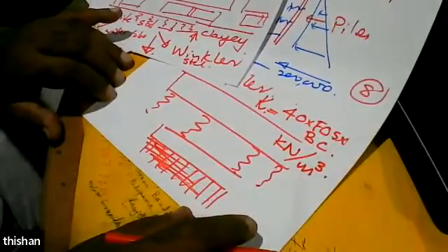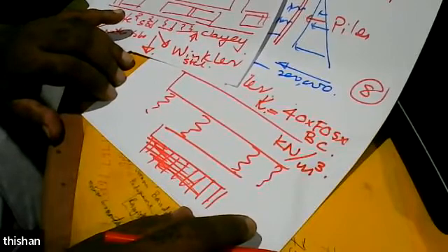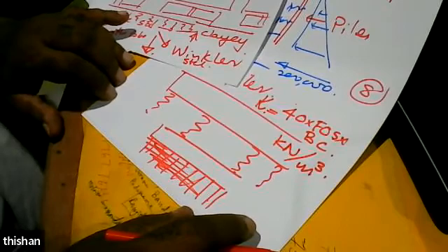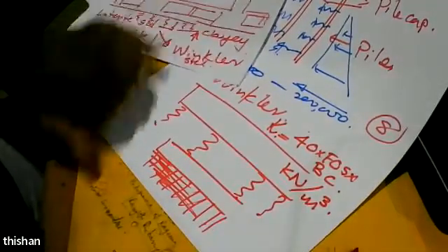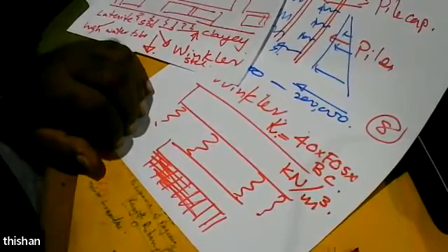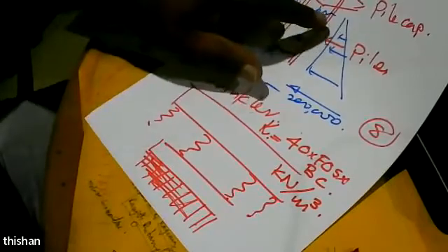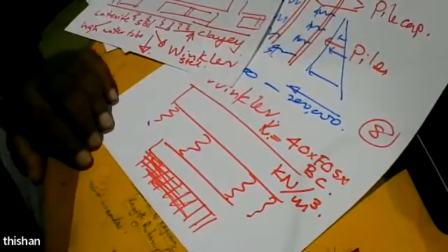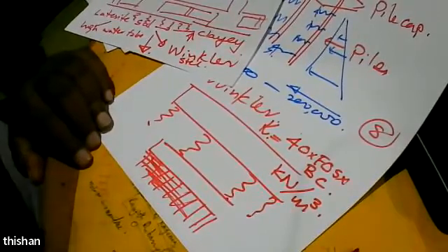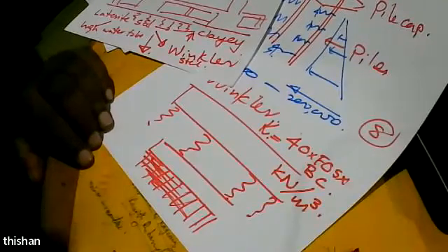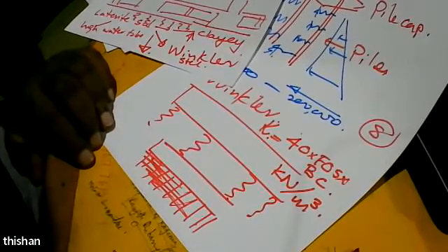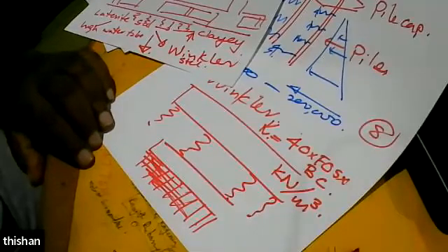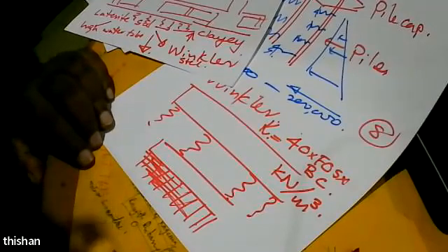But the lateral springs, the behavior is a little different, and there are some empirical type guidelines to decide the lateral springs, and it can vary between 20,000 to 200,000. But when it comes to vertical springs, there's nothing called vertical springs for clay soil. You have to model the soil by using what you call solid elements, and in solid elements you have to tell the stiffness or the E value, elastic modulus of the soil. And if you have any patches where the elastic modulus is different, that can be represented within the soil.